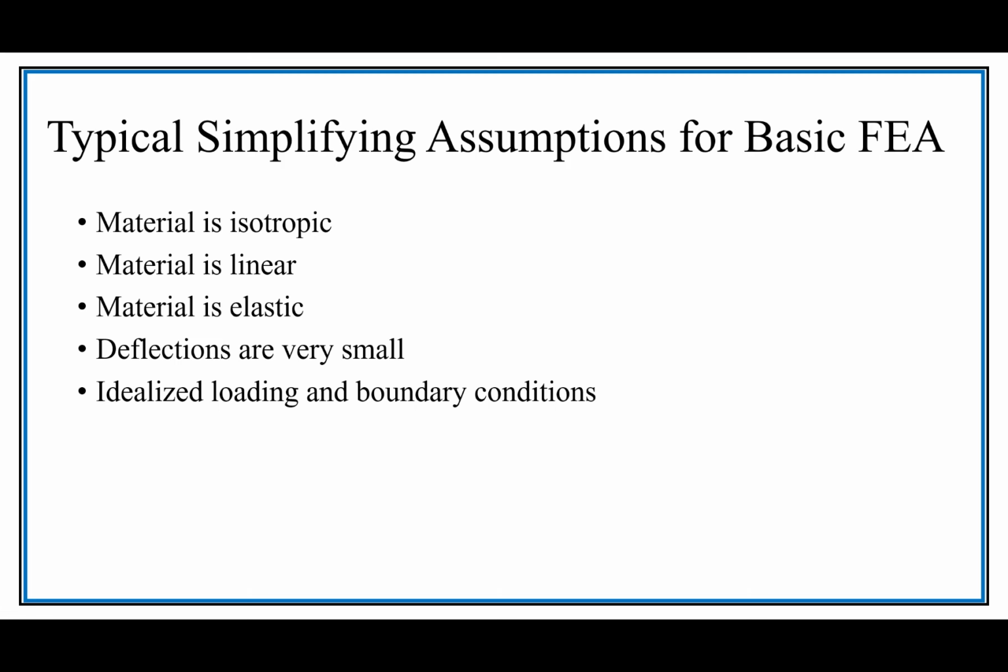We've idealized the loading conditions and the boundary conditions. These are very important things. We could go into this in a lot of detail about how we apply the loads and how we apply the constraints. And often that could be pretty important for a particular problem that we're working on. The loads are static, as if we've slowly applied the loads, so we're not thinking about dynamic loads, if we put them on suddenly with some type of impact.